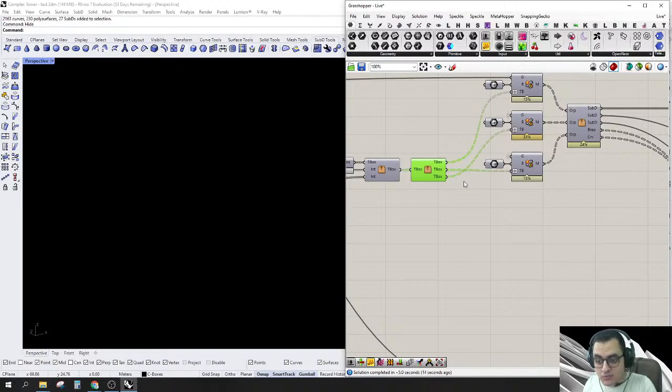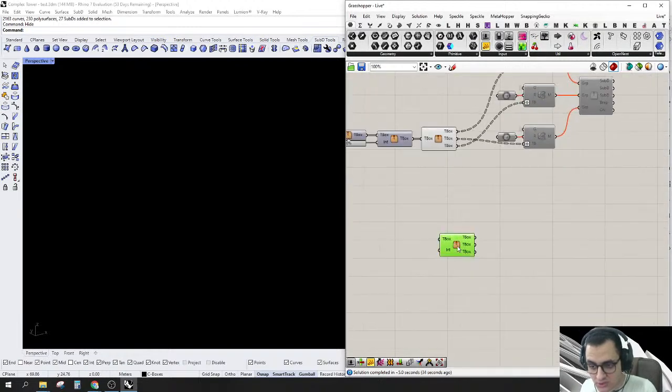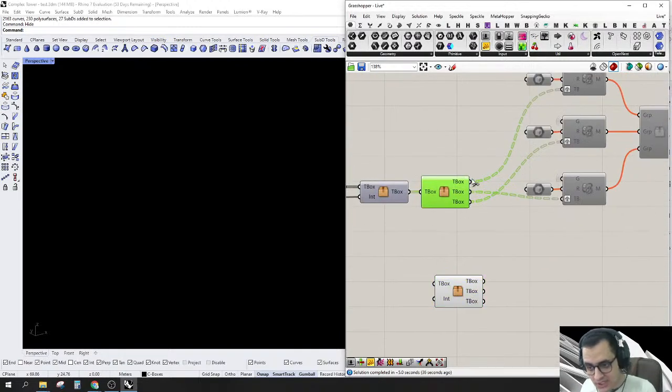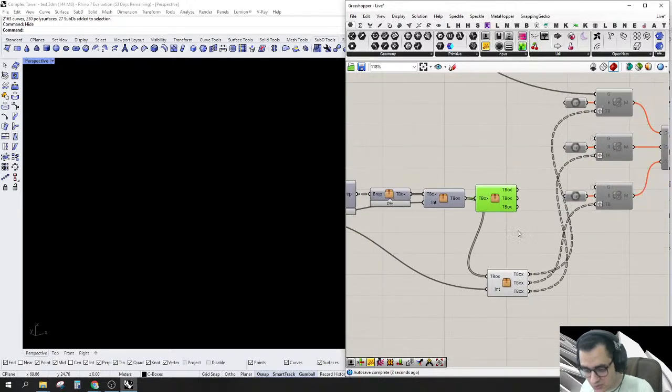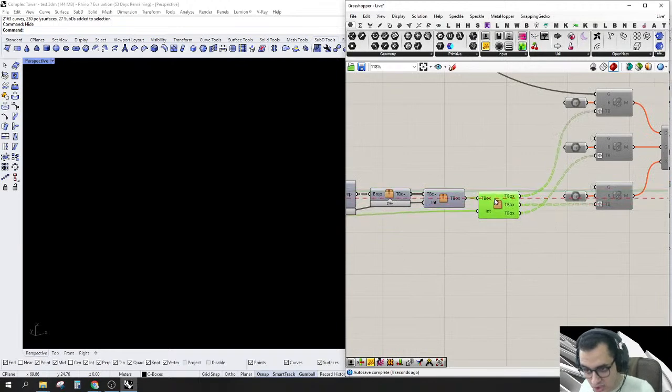So basically, if you misdone it like I just did, copy what you already done and Control Z until you go back to the original cluster, and simply Control V in the main canvas, and create a new cluster out of the new output. So now basically we will get this one in here, this one in here, this one in here, and go to this twisted box and input this number. And so let's hope everything is working according to the plan.